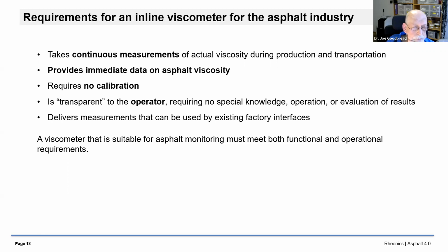They have to be free from calibration. Calibration is one of the most troublesome aspects of viscometers, and yet you can't go out in the field and pull out an inline viscometer at a remote site and do regular calibration work on it.